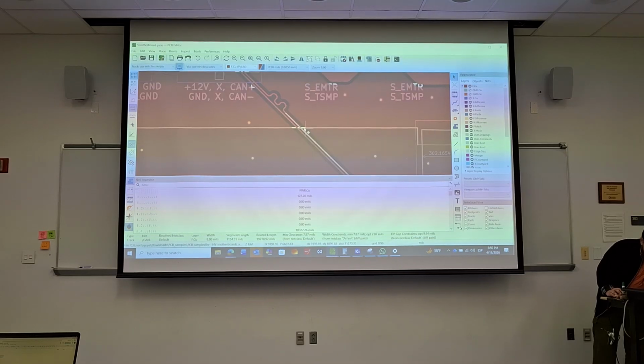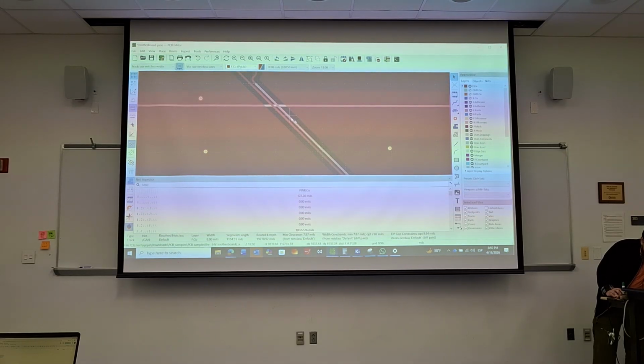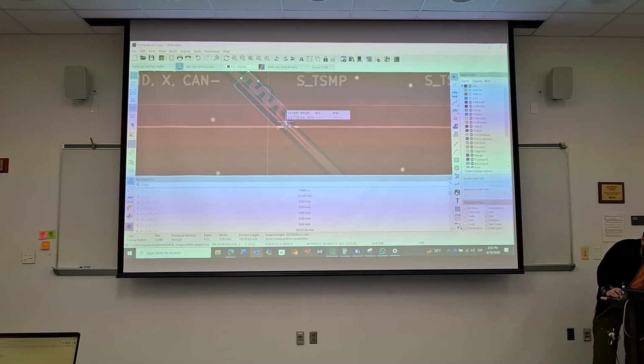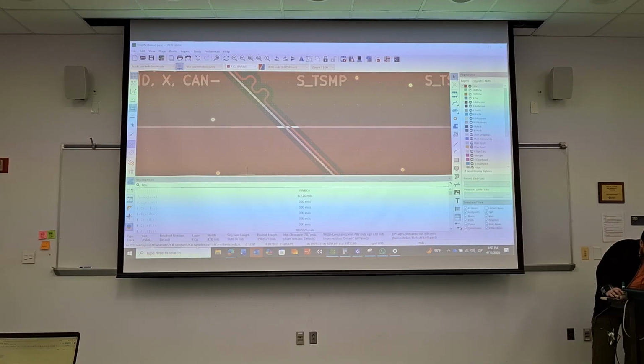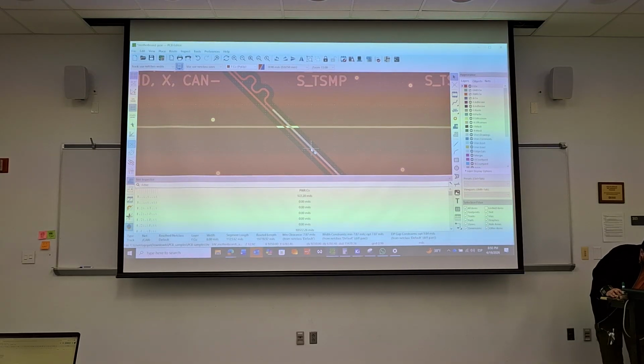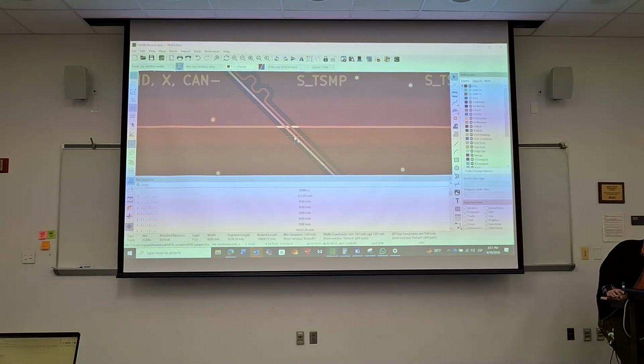And I'm not sure what KiCad does, but I think you manually tune it, right? So you manually choose how much tuning you need. And you can typically check down here the routed length. So this track is now 19,000. Am I reading that right? Yeah, 19,000. I guess 19 inches and 778 mils. And this one's 400 and... Well, it wasn't even tuned right.